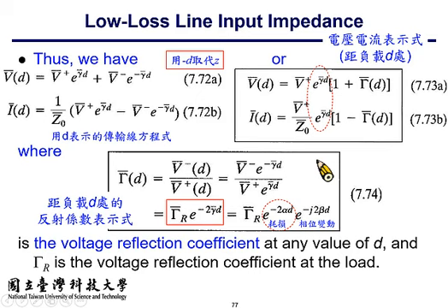How to fix that? Well, I've seen this many times. They draw a transmission line all the way from the antenna to the bottom to provide a connector, say an SMA connector. And with this modification, the S11 looks much better, like this. Why? Because the transmission line is lossy, it absorbs most of the reflected signal.